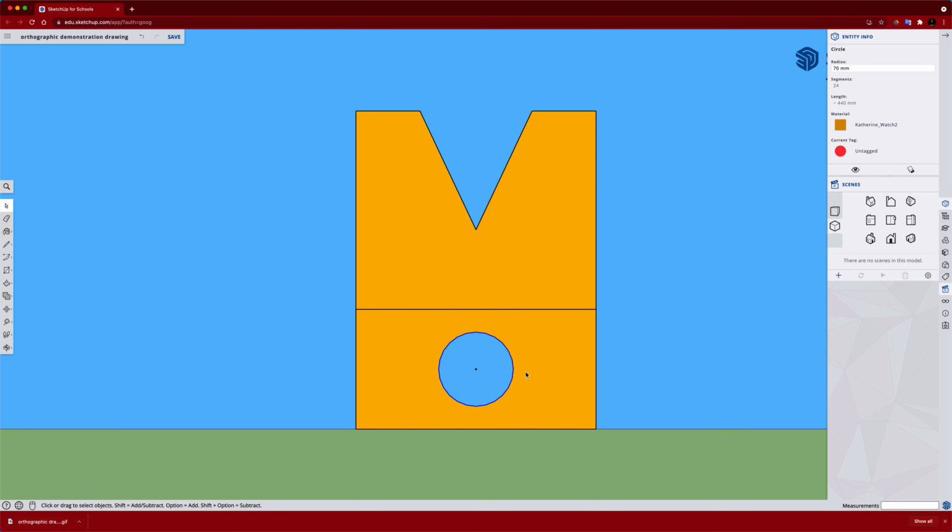Well, there's nothing I can click on, but what you do is type T for tape, go on to that center point, click, slide over, make sure it's on that red line, find the edge right there. It says that is 225 millimeters over. Now, I haven't clicked or anything, so I'm still attached. I'm going to go to the other side, and you can see that that is 225 millimeters.